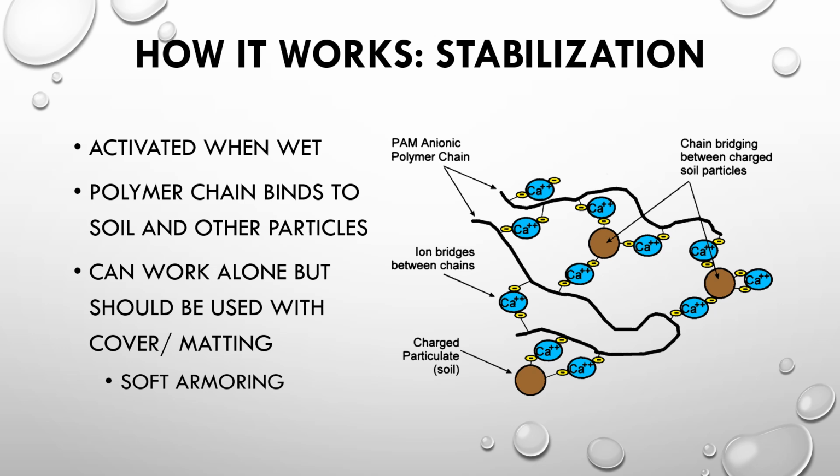It's really for both soil stabilization and water treatment. I like to say it's all about the agglomeration and pulling those particles together. So for soil stabilization, we have the granular form of the polymer. It becomes activated when it's wet. Those polymer granules will unwind into a long polymer chain that can then bind to soil, metal, other targeted particles, and hold them in place on the soil surface so that they're resistant to runoff and erosion when we have stormwater and rain events.